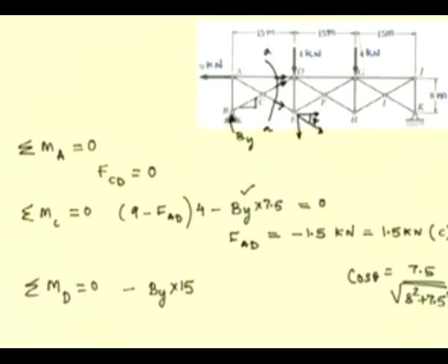So, the horizontal component of this force is going to have a counterclockwise moment. So, it is a positive quantity FCE cos theta, and the moment arm is 8 meters, and from this equation we determine FCE as 11.9 kilonewton, and since this is a positive force, it is a tensile force. So, this problem illustrates how we can use this method of section to determine the forces.